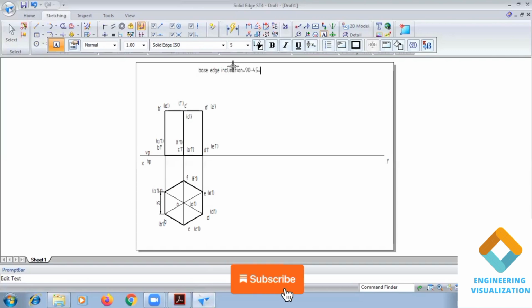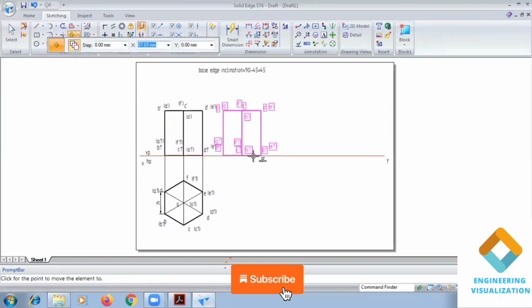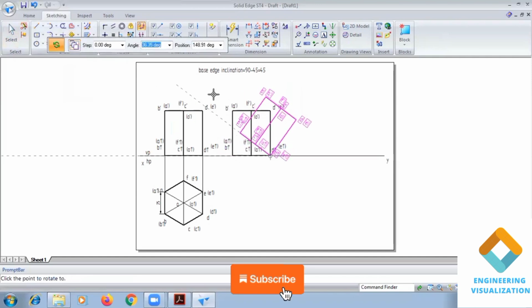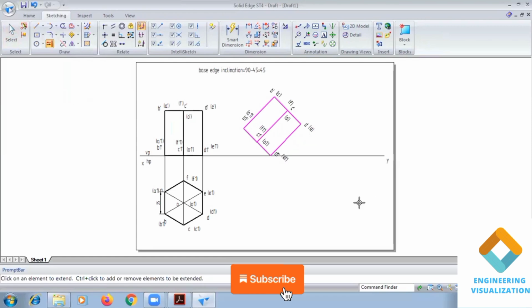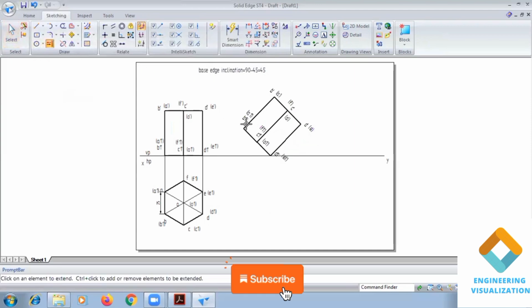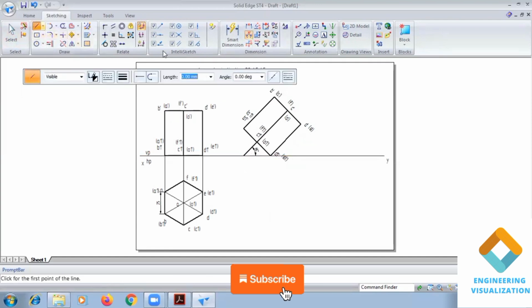We have to incline this with respect to the base edge, at an angle of 45 degrees. Then use the extend command to extend the axis and find the angle of inclination.